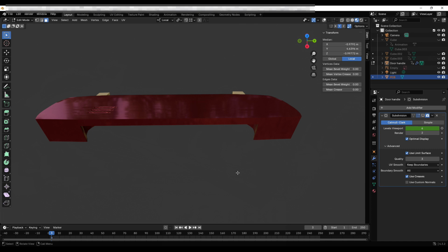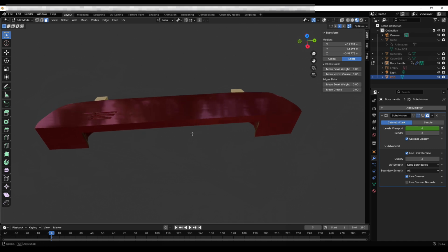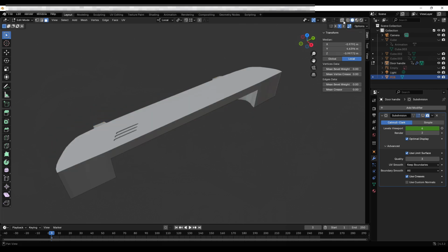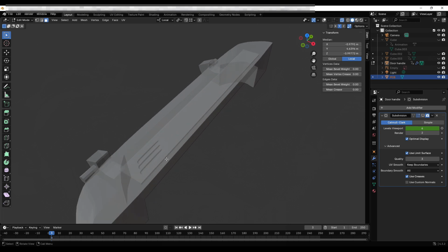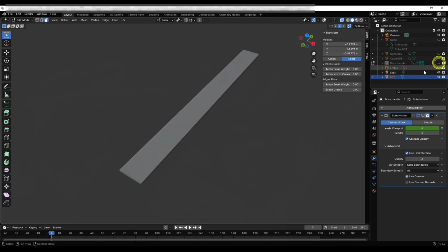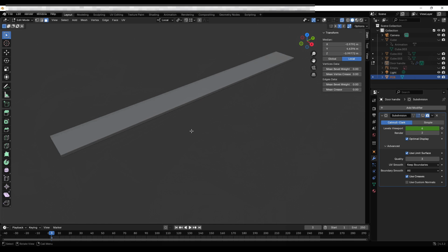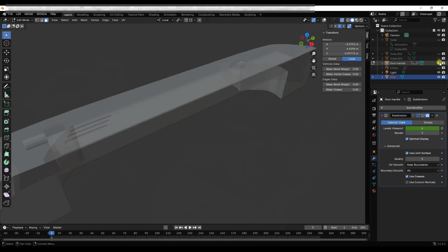One thing that's going to ease the import of the model is that you add the PCB outline to your design. If your official design files cannot have this, make a copy where this is added. You will soon understand why. Here, the PCB has been added as a part of the structure. This is a simplified model where the entire volume of the door handle is filled with a non-conductive material. Hence, the PCB has contact with the door handle material everywhere. Normally, that's not the case, but for this demonstration, it makes no difference.